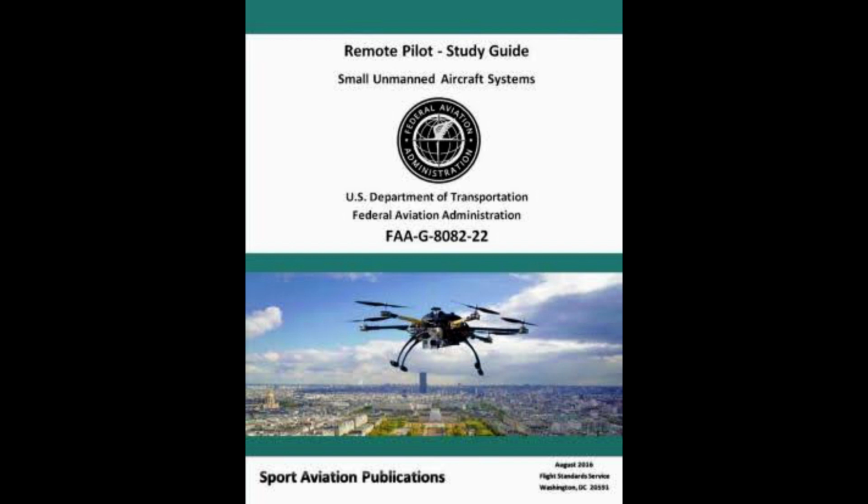Adverse balance conditions, i.e., weight distribution, may affect flight characteristics in much the same manner as those mentioned for an excess weight condition. Limits for the location of the center of gravity, CG, may be established by the manufacturer. The CG is not a fixed point marked on the aircraft; its location depends on the distribution of aircraft weight. As variable load items are shifted or expended, there may be a resultant shift in CG location.